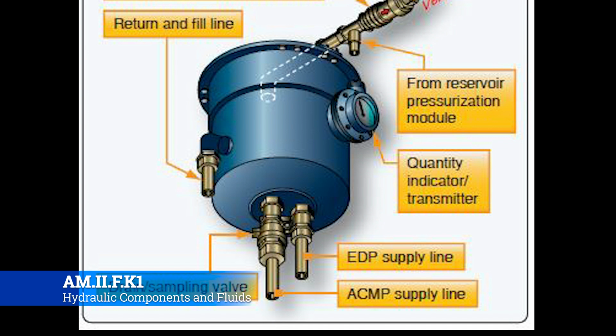So kind of like your hot water heater has a little poppet that will pop off if the hot water pressure gets too high. The reason being is that you don't want to over pressurize basically what would become a pipe bomb inside of your landing gear. So if it starts to get too much, that relief valve will pop and let the pressure go out. Then you'll have to deal with not having any hydraulic pressure as opposed to literally blowing the fuselage in half.